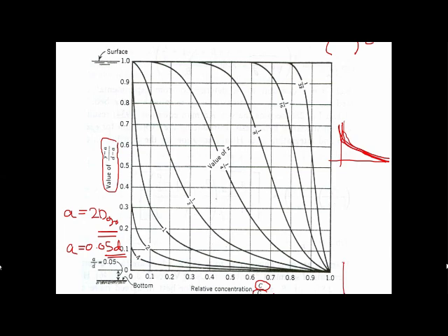So if you have a profile like this, and you take 0.05 multiplied by D, which is your bed layer, your concentration will become like this, and this concentration a is at this point. Okay, the concentration C is along this curve. Along this curve. So this is the Rouse profile, the original Rouse diagram or Rouse profile we call it.